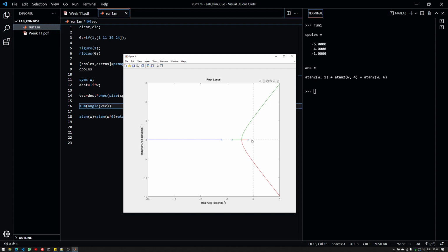So it will determine the pole pair that will be on the j omega axis. So I don't have k yet. I should calculate k based on omega, but that'll be easy. So the hardest part here is to determine where the passage occurs. Therefore, this angle condition determines the position where this happens, and then we will look for which k causes this.